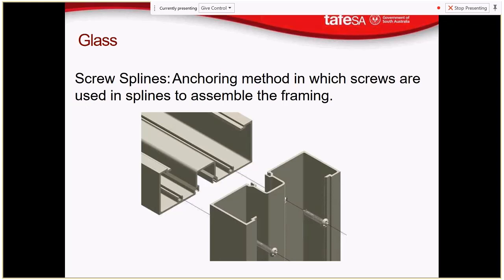That's what we see. But inside of here, we have these things going on. So our accommodations for the glass. Then we also have these little channels here, and those little channels are for fixing them together. So those screws go straight through that mullion, and they will screw straight into that head.